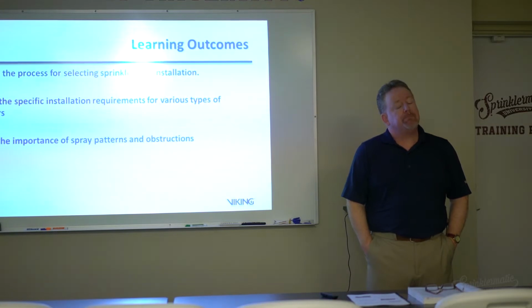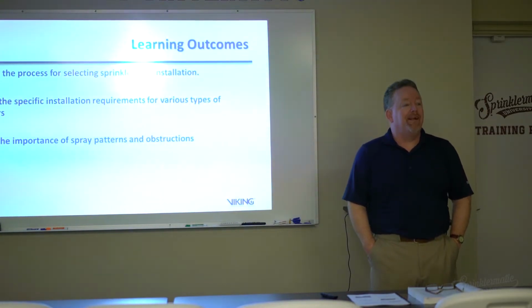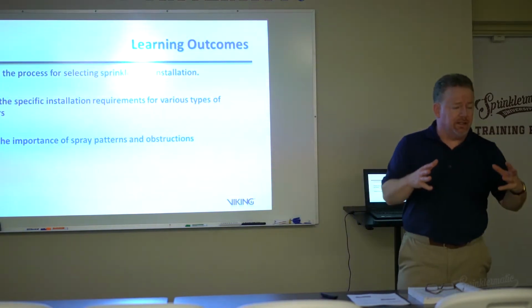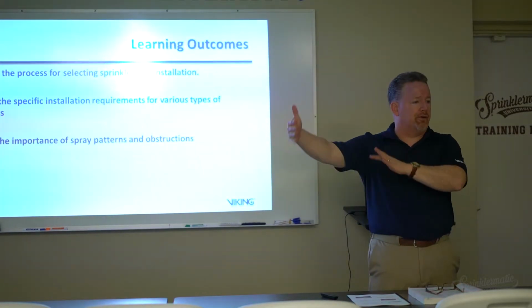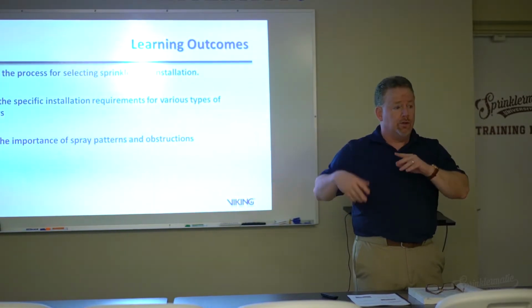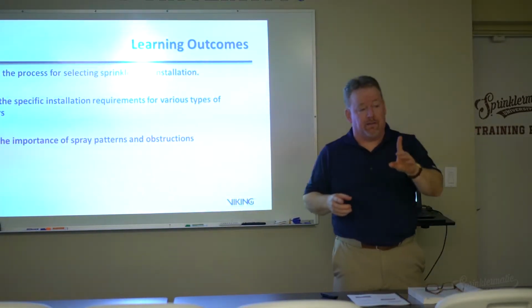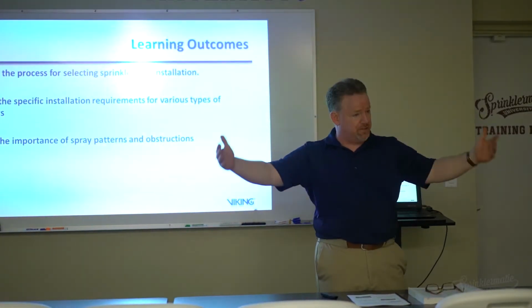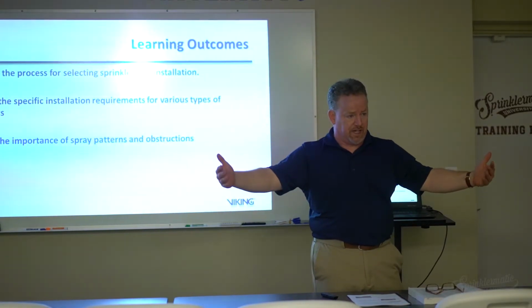If you wanted to change the hazard at a later time, is the piping adequate to go to, let's say, a medium hazard or a high hazard? Not a high hazard. Can you change out your sprinkler heads to meet a higher standard? You don't have to. Remember that in an ordinary hazard group 1 or an ordinary hazard group 2, you can use quick response as well. It wasn't built as a light hazard, but to your question, you don't have to change out the sprinklers from quick response simply because the hazard classification changed.